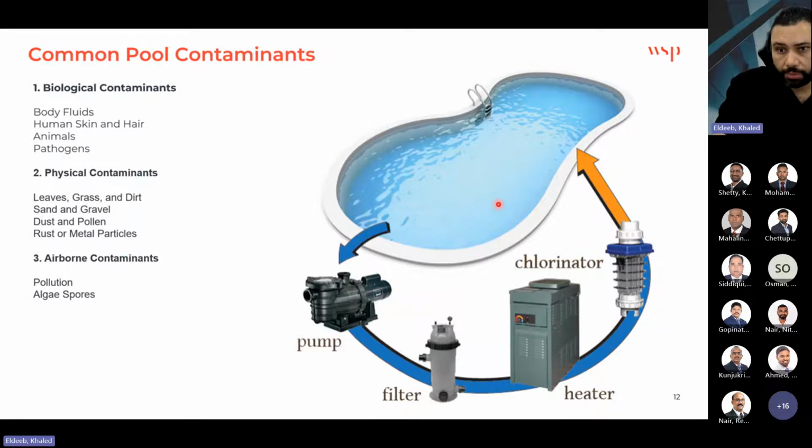So we have to provide a treatment solution to maintain the quality of the water. Our job as mechanical engineers is to remove all of those contaminants. The whole volume of pool water shall be filtered completely at least 3 times per day, and the more the better for water quality, such as 4 times, 5 times. But this depends on several factors, and we are going to see in detail in the next session, which is called number of turnover period.